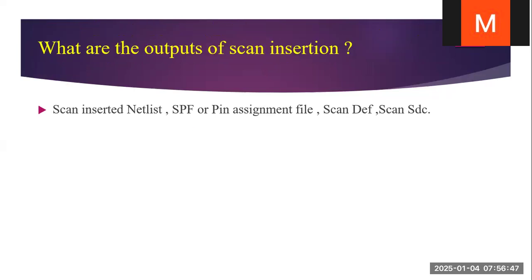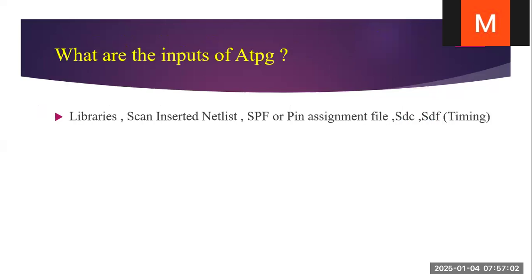What are the outputs of scan insertion? The scan inserted netlist, the SPF pin assignment file, the scan DEF file, and the scan SDC, which is the Synopsys Design Constraints file. It contains the false path and multi-cycle path information.